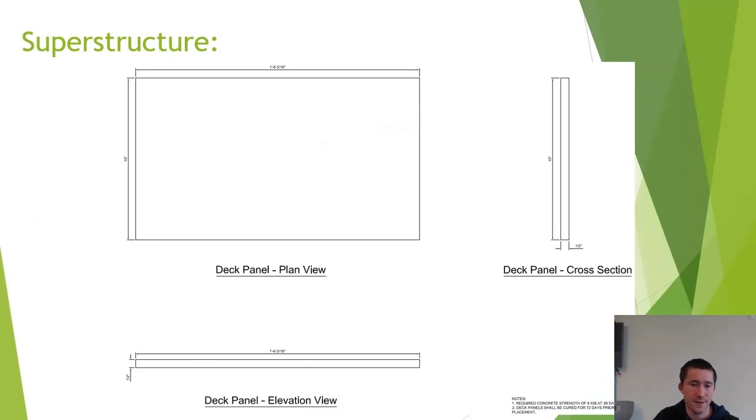Here are the outlines of the precast deck panels, currently set as 6 inches deep to span 10 feet in the transverse direction and 17 feet in the longitudinal direction. Design checks for the deck have also not been completed. As you see, the rebar is not drawn in yet.